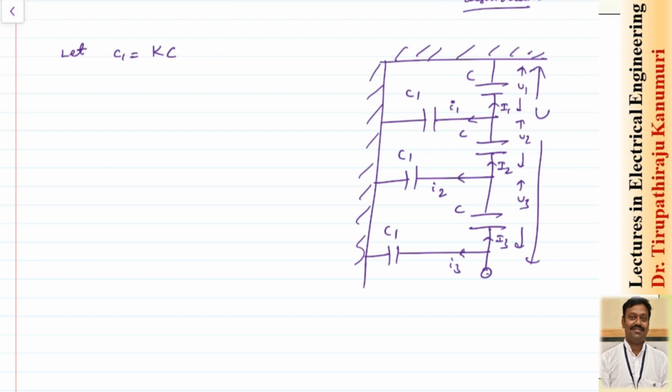Here you have to remember that the voltage across this shunt capacitance will always be the voltage between the pin and the reference point or the ground point. You can see this reference point is connected to this reference point. So, we can tell that these two are at the same potential, and we have to calculate accordingly. Let us keep the nodes as A, B, and let us take this node as C node, and there is a ground potential or the reference node.